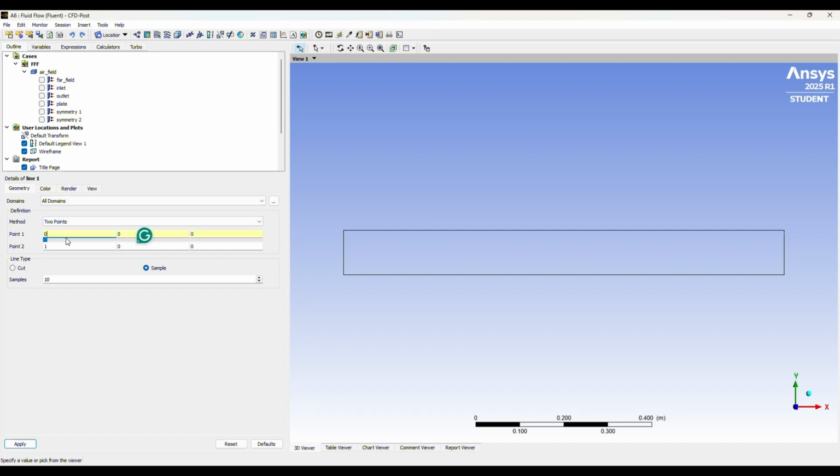So our object is 100 centimeters long. We want it at 35, so we're going to put it at 0.35. That's 35, and 0.35. This one is wrong. I forgot the decimal. And it's 10 centimeters tall. So we're going to do 0.1, like so. And then we're going to do 100 samples. So there we go. We got our first line in.